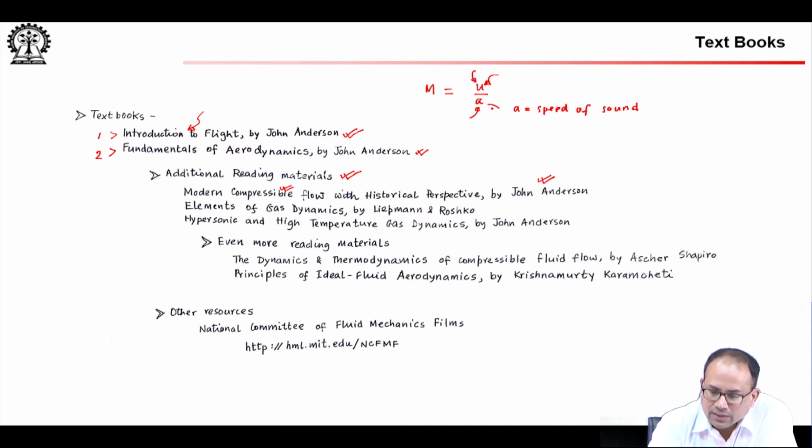Okay. So, this A, which is the speed of sound, you have to calculate it. I should say it is the local speed of sound. Okay. So, if you have an aircraft that is flying at 32,000 feet at a given velocity, the Mach number of the aircraft, which we often abbreviate like this, would be the velocity of the aircraft divided by the local speed of sound.